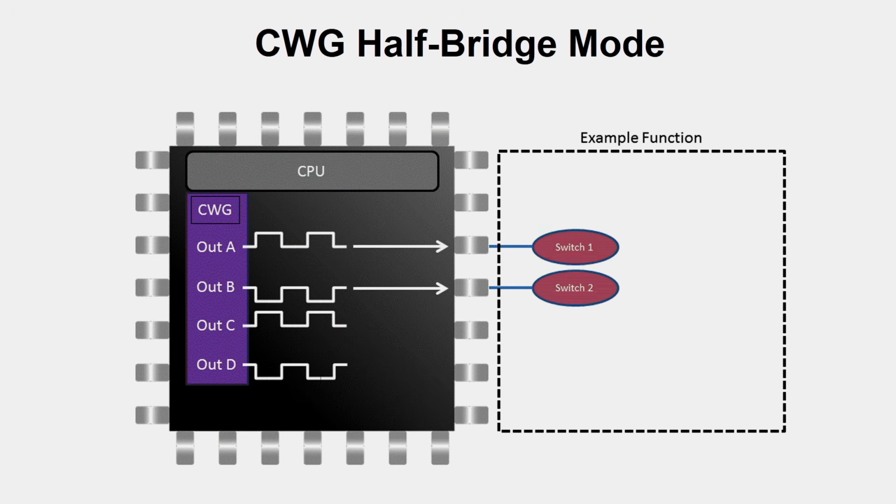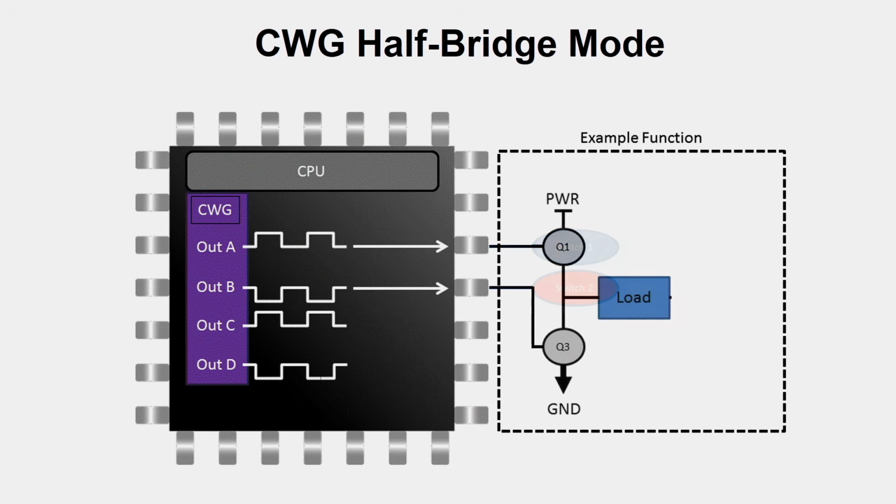What we mean by complementary is the lower bridge of your output is exactly opposite of your higher bridge. Okay. And usually it's used for driving a half bridge circuitry. But normally, if you want to drive that, somebody says, okay, I can just invert my PWM to do it, right? It's the same thing, but actually it's not, because there are some timing issues here. If you switch your two PWMs together, sometimes they're on together. At the same time? Yes.